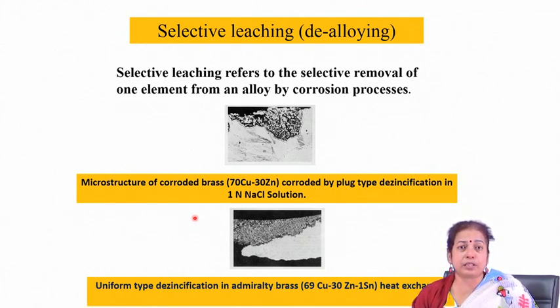But otherwise, if you are interested in taking care of this problem by surface treatment, you have to go for typical surface melting operation, by the application of a high energy beam like laser or electron beam, where you melt the surface and then quench it very quickly, so that there is no chance of any chromium carbide precipitates, and that particular steel on the surface is highly free from chromium carbide. So, whenever intergranular corrosion occurs or is observed, it is very important that you find the solution very quickly, so that this steel does not undergo any kind of corrosion in the service environment.